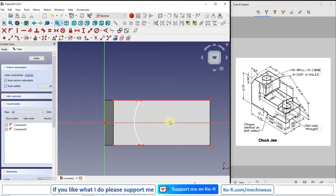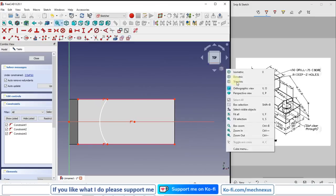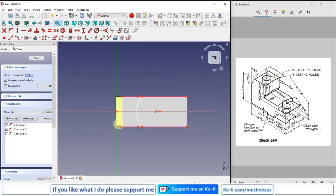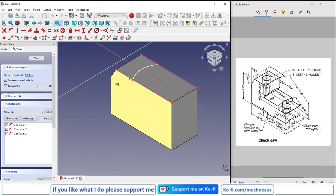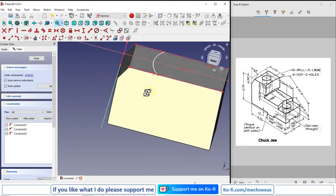And then I will make this arc center point coincide with my axis. And now we will read our dimensions. So from the edge it is 1.75 inch. So I will project my edge here. If any difficulty, switch to the isometric, rotate the model and select the edge. So you can see that it has been projected.